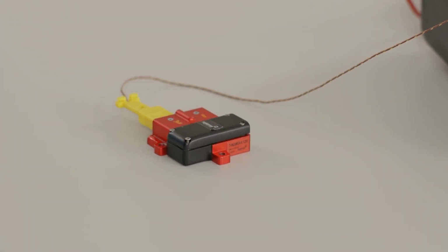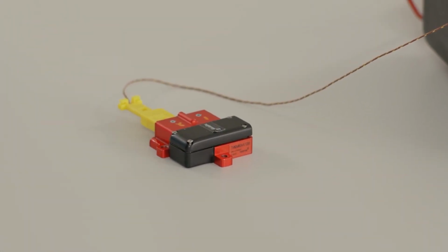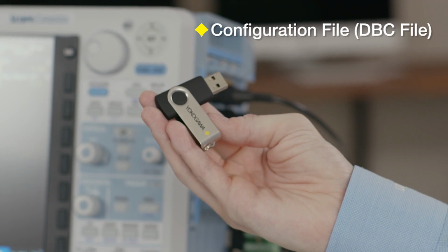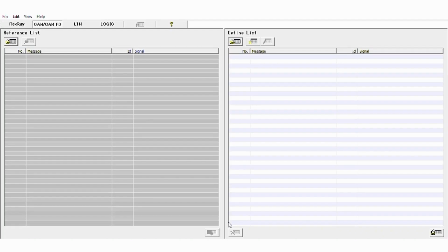The CAN modules we're using should only be installed in slots 7 or 8 of the ScopeCorder. Lastly, we'll want an industry-standard DBC file with message definitions for the CAN sensor. Now, we'll load the DBC file for the Texense sensor into our symbol editor software to perform a simple conversion to the SBL file for our DL950. This software is available for free on our website, and a link will be provided in this video's description.